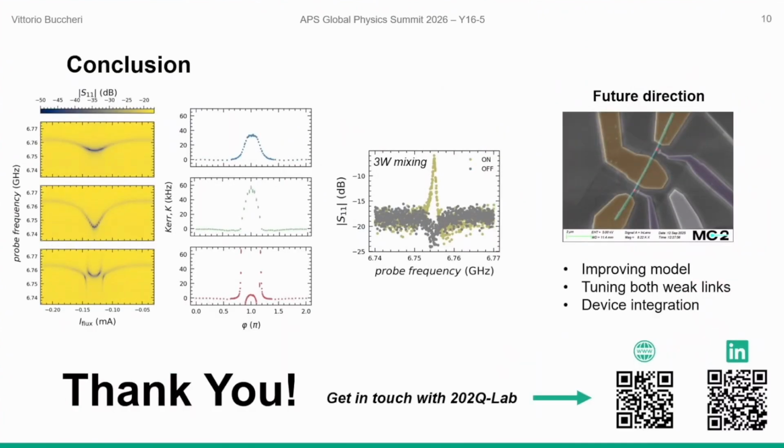So, the conclusion: I showed you how the semiconducting junction is affecting the properties of a resonator. I showed you how it changes the frequency shift. I showed you how we can tune both the Kerr and the three-way mixing with the phase and the gate.